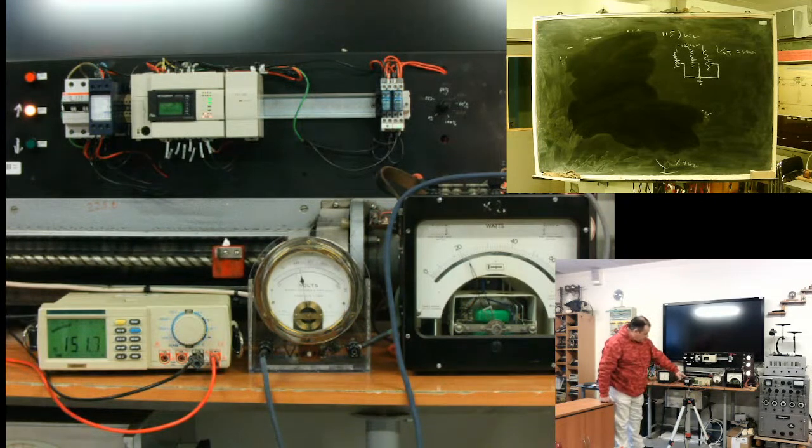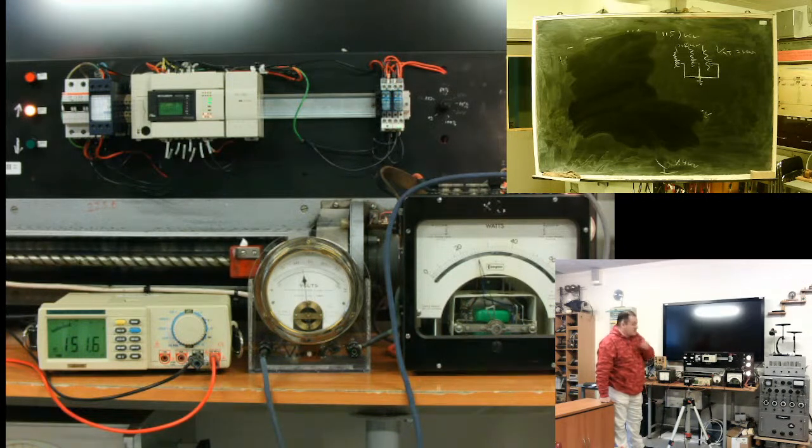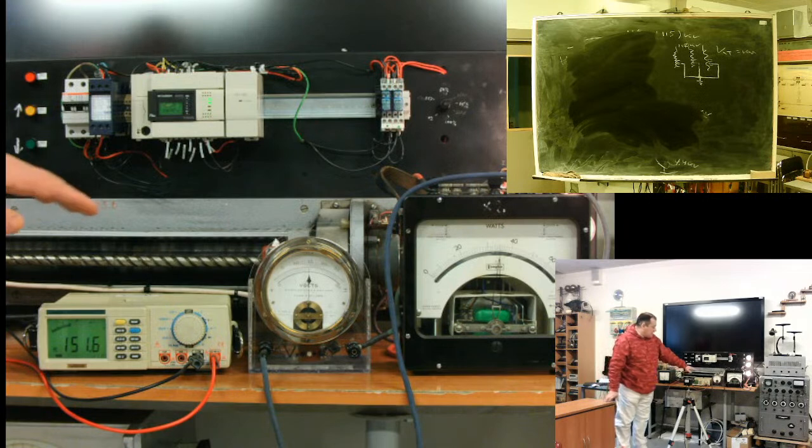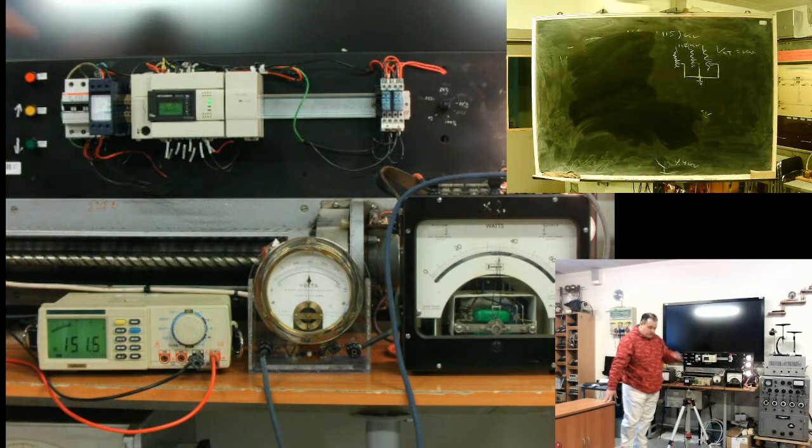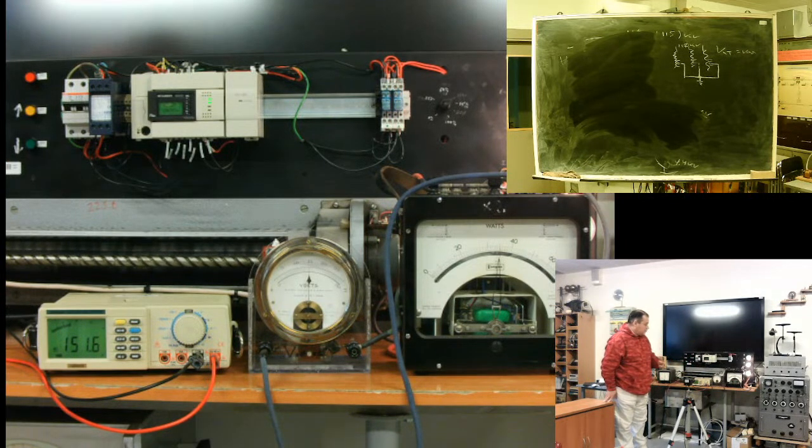Voltage 161. For the control system, there is no difference whether voltage changes due to load increase or primary voltage. You can see the control system returned the voltage to the set point, 150 volts.